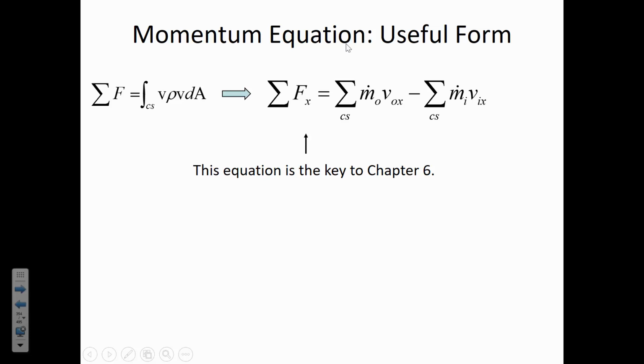So this is the form of the equation that we're going to be using for problem solving, in the same way that you kind of had to take the theoretical equation for Euler's equation and then apply it to a direction. You know, this is independent of direction. But if we wanted to apply the momentum equation for forces that occur in the x direction, then this is how we would do that.